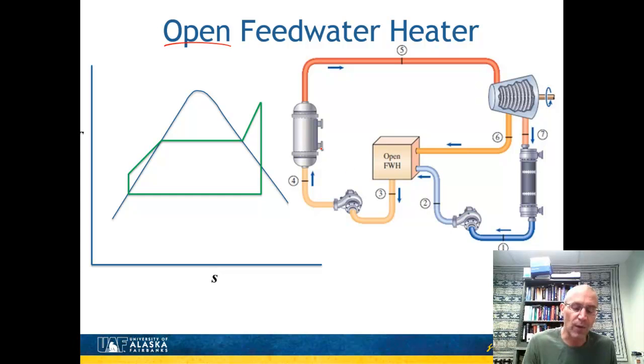And so here's our Rankine system with a feed water heater. I've got my boiler here on the left. Here's my turbine, a single turbine, and the condenser. And what I have now is this box, which is called an open feed water heater. You can think of it as just a large tank with 3 openings in it, 2 that go in for an inlet and 1 that comes out. It's nothing more than a large tank. And so what I'm doing is halfway through the turbine at intermediate pressure, I bleed off a fraction of the mass flow rate. I'll call that fraction y, some number between 0 and 1. It's a fraction of it, and I add it in here. So this is going to be at some medium temperature. We call it Tm.